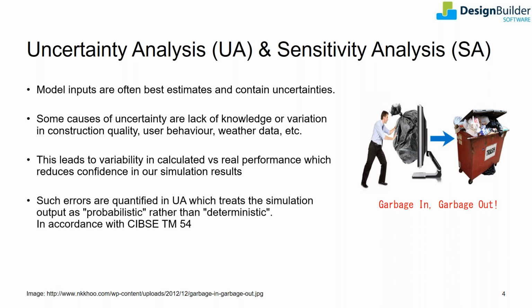While it is not possible to improve the estimates for inputs at the design stage, we can still determine the confidence level and the ranges within which their values would lie. For example, it is not possible to say that post-occupancy, the users will maintain the heating set point temperature at 20 degrees, as assumed by the designers. However, it is most likely that this value will be between ±2 degrees, with the highest probability that it will still be 20 degrees. Uncertainty and sensitivity analysis factors this in.